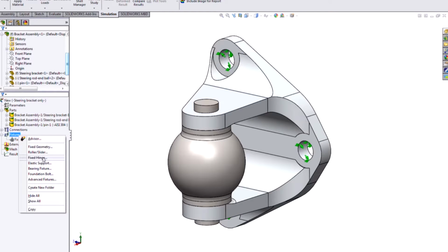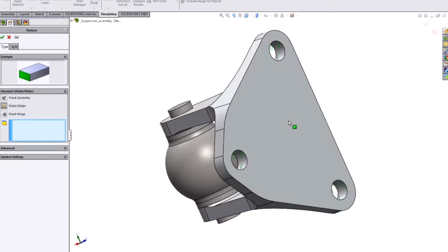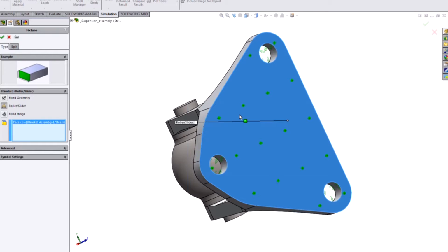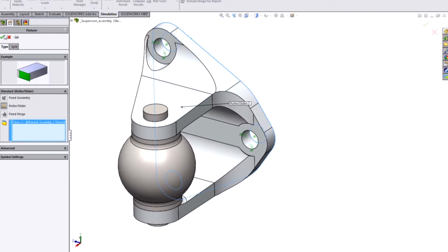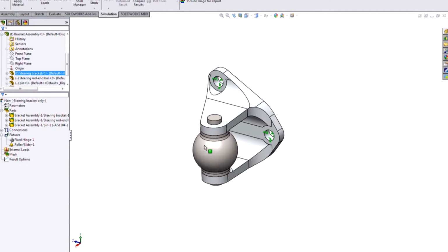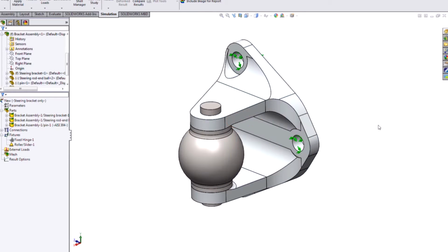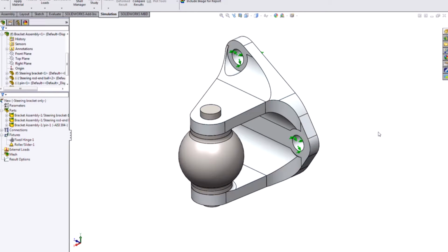Okay, I might also consider the back of this is up against a large, broad, stiff object. So I'm going to prevent that from moving off plane. And we can actually independently control the degrees of freedom of faces or edges or vertices in the model, either based on a Cartesian, cylindrical, or spherical coordinate system. It's a really rich control there.